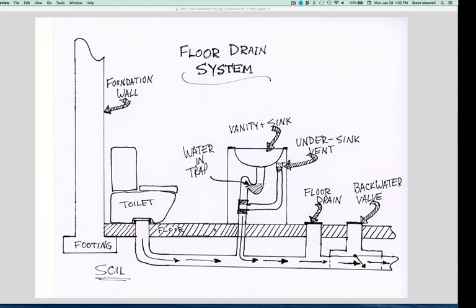So to add these pipes, you're going to have to break up channels through the concrete so you can dig down into the soil that's underneath your basement and add these pipes. They need to be sloped in the right direction and all that usual plumbing stuff. But the purpose of this video is just to give you an overview of what has to happen. So you need to break up the floor, install the pipes in a rough-in sort of way. So they would end somewhat above the floor, and then these other things would be added later. Here there's a flange, a toilet flange, which would be kind of at floor level, and the toilet would bolt to it, and it would make a sewage connection that would work and keep things contained.